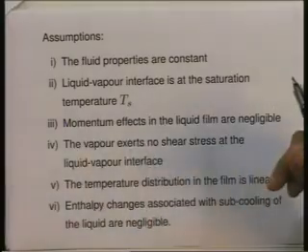The liquid film, as I said a moment ago, which is the condensate film formed, is a very thin film, and Nusselt said, let us assume that the temperature variation in this liquid film is linear, it is a straight line. So, we will make that same assumption that within the liquid film, the drop from T s to T w over the thickness of the liquid film, which is delta, will be a straight line. Again, probably an exceedingly good assumption to make.